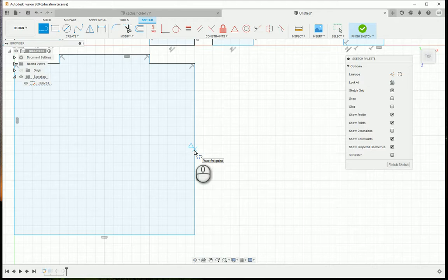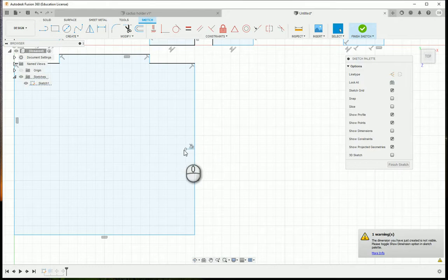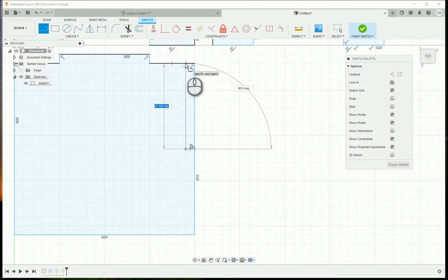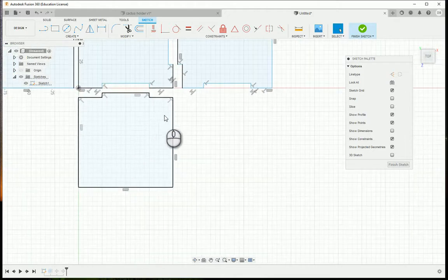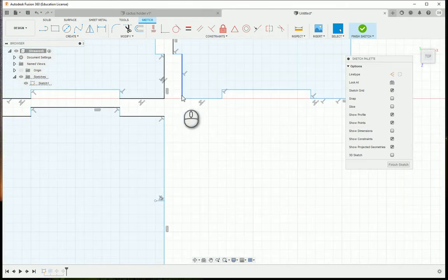The other thing I need to be aware of is that I've removed 5mm off of this piece here. So the center of my line now will be higher up. So the distance from here to here is now 47.5. But it should be 50, because it should be halfway. And that's because we've removed this 5mm of line just here. So this is going to cause me some problems when it comes to placing this in the middle. Now it's okay though, because I did exactly the same on this one.